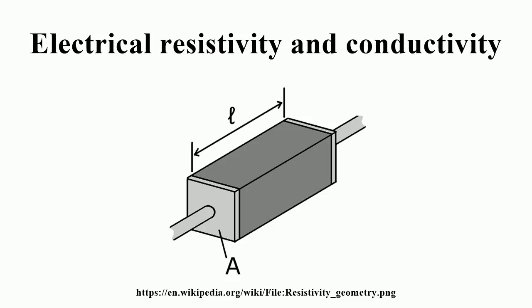In extrinsic semiconductors, dopant atoms increase the majority charge carrier concentration by donating electrons to the conduction band or accepting holes in the valence band. For both types of donor or acceptor atoms, increasing dopant density reduces resistance. Hence, highly doped semiconductors behave metallically. At very high temperatures, the contribution of thermally generated carriers dominates over the contribution from dopant atoms, and the resistance decreases exponentially with temperature.